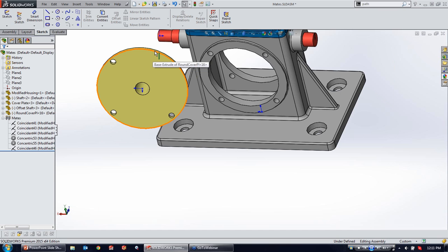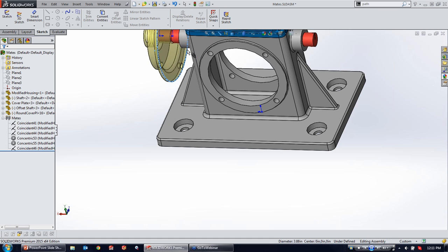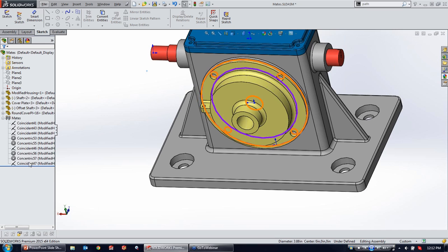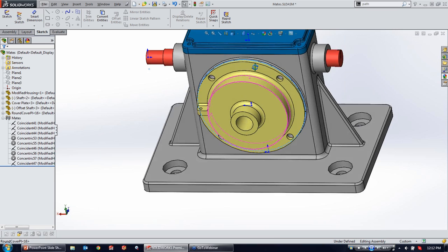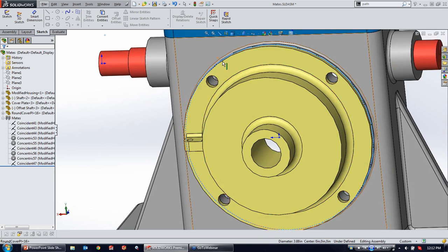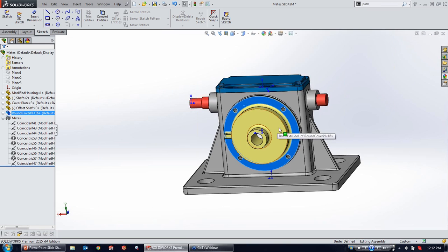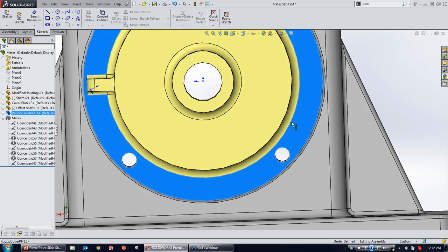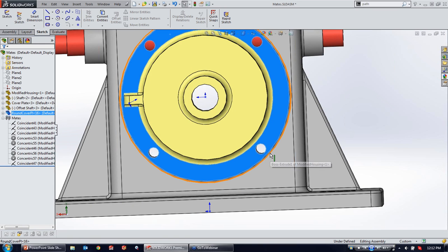So when I do this, I'm going to select the edge because I want a version of a peg and hole here. I'm going to hold down Alt and come to the outside edge of this. So now what I have the ability to do is snap both to the face, but also to match up my hole pattern. Angle it correctly. There we go.